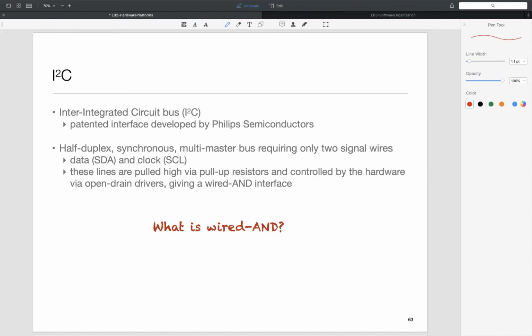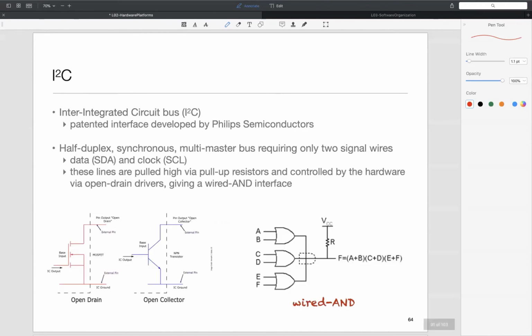So you would see a lot of sensors on the boards and all. I wouldn't be surprised if the sensors in our little Arduino are also I2C based things. It's very common. Okay, and the way they work is that all the different devices' output signals are all ANDed together into a single wire. So kind of the idea is that this wire out here is pulled up, and then individual devices, only one of them would be driving it at any given point in time. So essentially, this is how you get the ability to have multiple devices sharing the same bus.